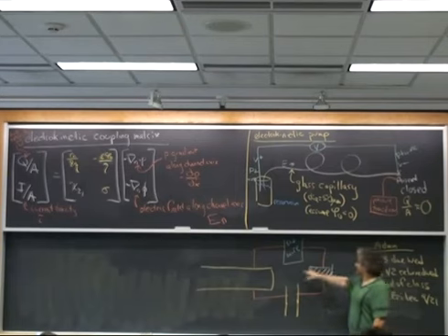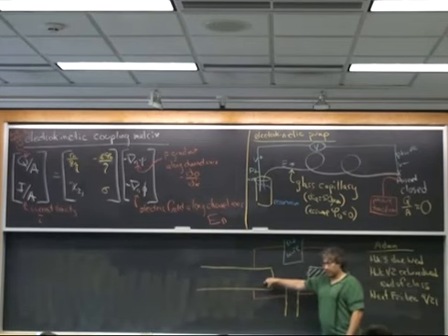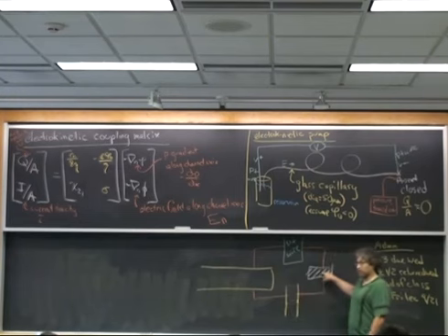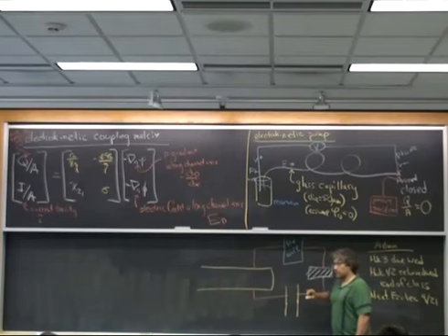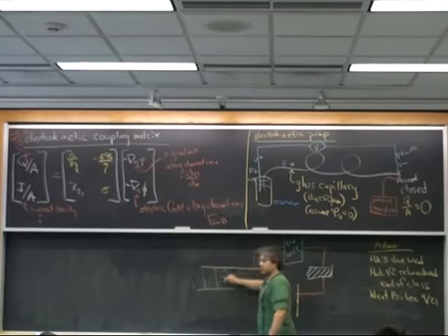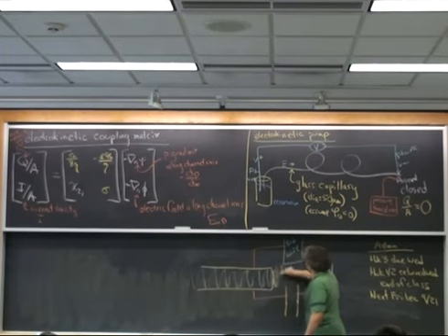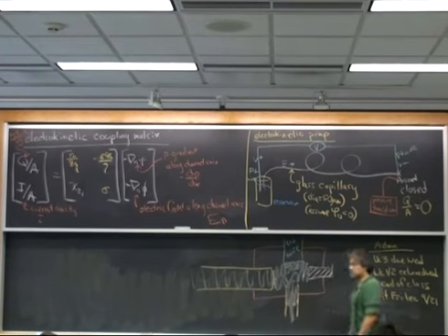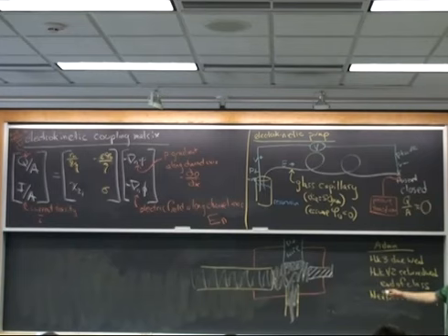And so if I had a 4-port connector, I would connect a platinum wire in one of the outputs, my capillary input in another one. This would be another tube that would go to the pressure transducer, and I'd have one extra, and I would just put a plug in. This is all the same electrolyte. So the electrolyte is throughout this tube. This electrolyte needs to be filling this enough to make electrical contact with this platinum wire. The plug doesn't matter. This electrolyte bath is presumably then continuing through here and connecting to the pressure transducer. The pressure transducer doesn't really care about whether it's liquid or solid, but in this case, this would be a pressure transducer designed to work with liquids.